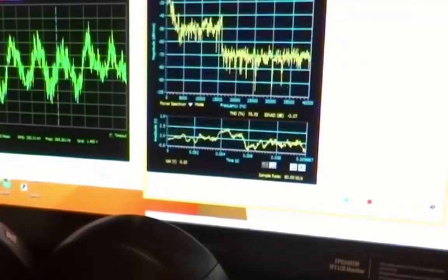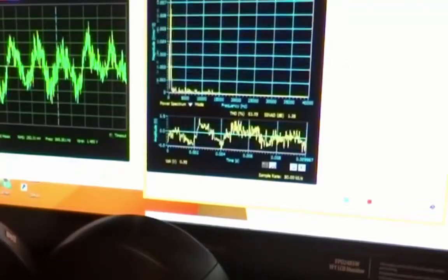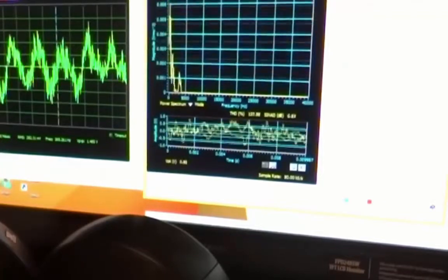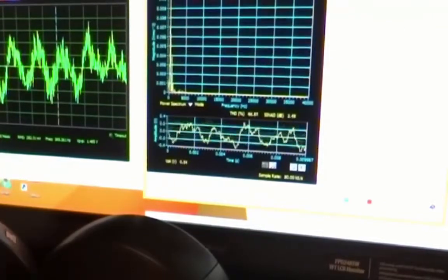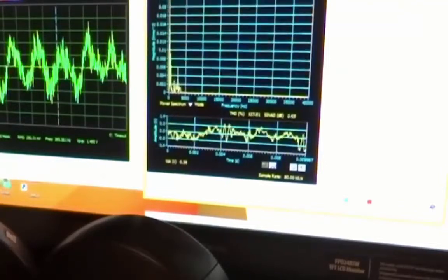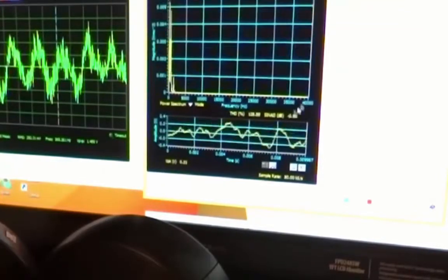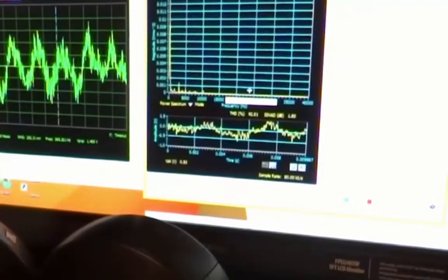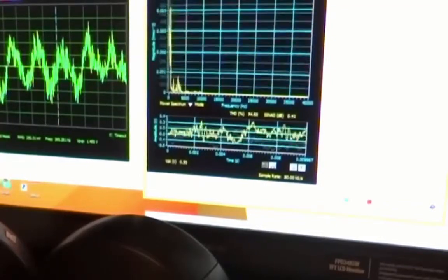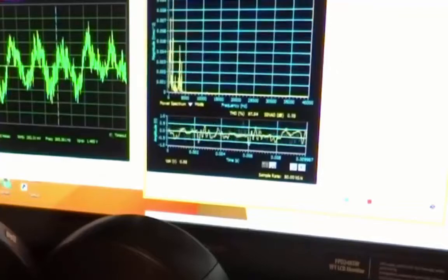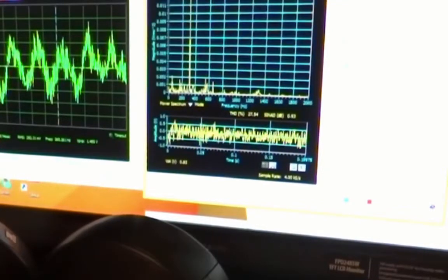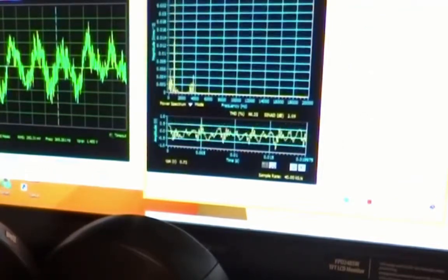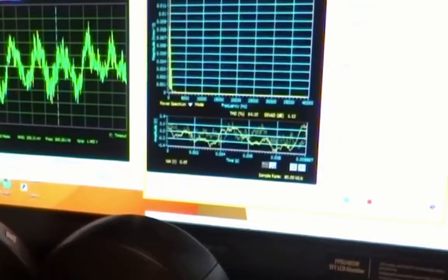You can see a little more detail if I put it on a decibel scale, but I found for our purposes for this lab, it's actually best to see these things on a linear scale. I've also put the averaging mode, which is usually set to something like RMS, to none. This frequency span I've set to 40 kilohertz, so this can reasonably represent a fairly large range over the course of doing the following experiments. If I simply wanted to look at audio signals, I would probably set this to 20,000, but it will be useful in a bit to have this at 40,000. We'll leave it there.